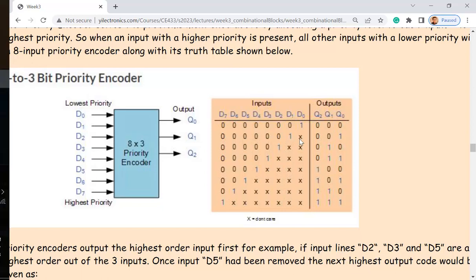Keep in mind, when you convert the truth table, a little cross means don't care. When you are converting a don't care to a min term in the logic function, you just don't care about that. For sure, you don't care about it, which means you just don't list it. Or you can put a 1 there, or a 0 there, it doesn't matter.